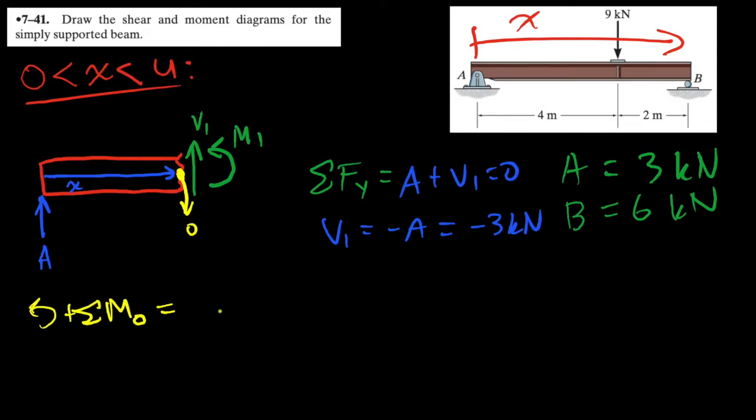So, if I want to calculate the moment contribution of A, then we are simply going to look at its clockwise contribution. So we say negative A times x, that is the contribution for the moment of vector A. And again, just to drill this point in, we're simply looking at the force itself times the distance to the axis of rotation. So basically the moment arm.